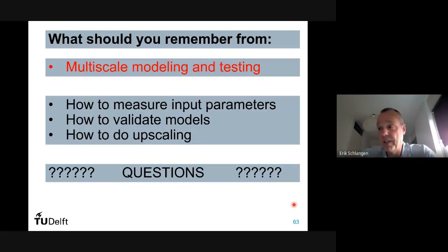If you put air bubbles in, then you have a different microstructure, and you can just follow the same procedure to scan your material, put these air bubbles in your microstructure, and do the simulation and see how your material responds to fracture tests. So that's similar, and you can apply that to all different kinds of materials where you change the local properties. So that's the beauty.